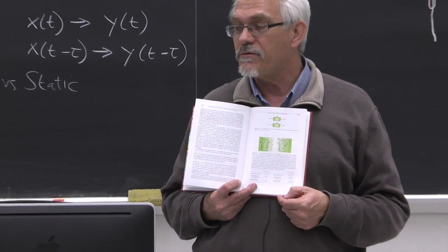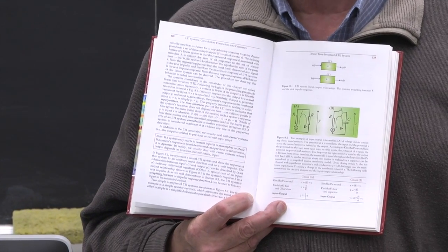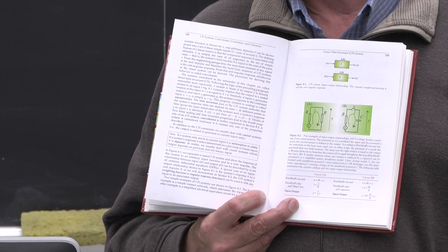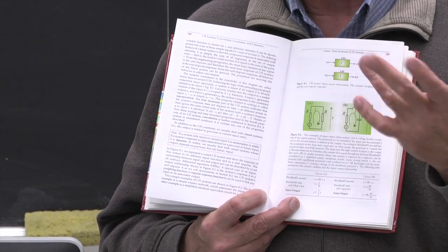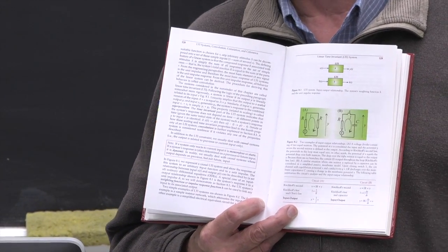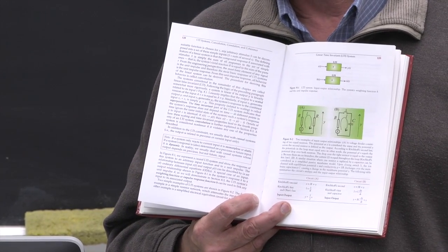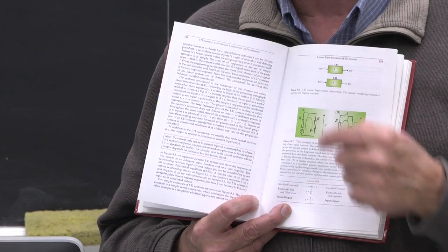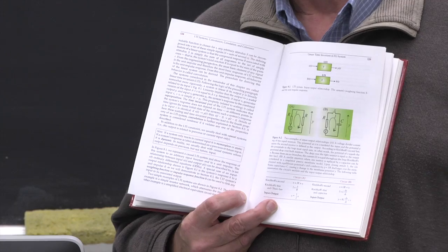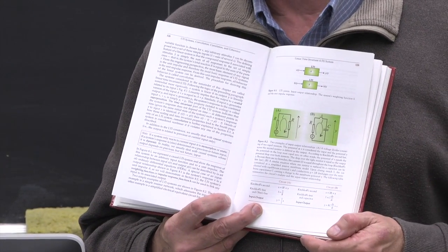In figure 8.2 you see a system where we have two resistors in series, and whenever something happens in the potential of the battery X, it will be immediately reflected in the output of the system, which is the potential over one of the resistors. So there is no memory, it is instantaneous, and that's a static system.